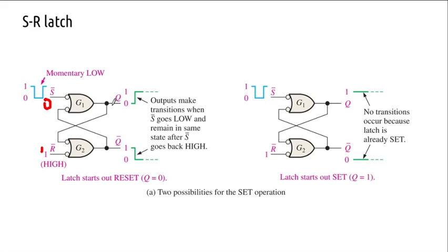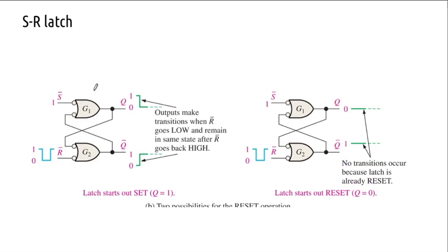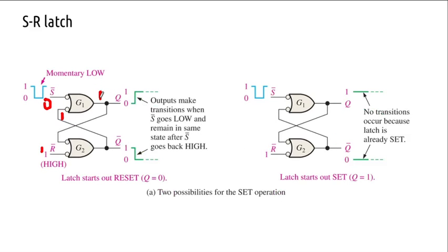Now again I start out from the opposite end. This is going to be 1 and NAND, this is going to be high. No, I'll start out from here, it is the reset condition. So wherever Q bar is 1, that is what is fed back, that is the trick inside it. You might be confused to always start from the top. So I'll just feed back this one here, so the output is going to undergo transition to high. After NAND, the output becomes high. When this 1 is fed back here, the output becomes 0.